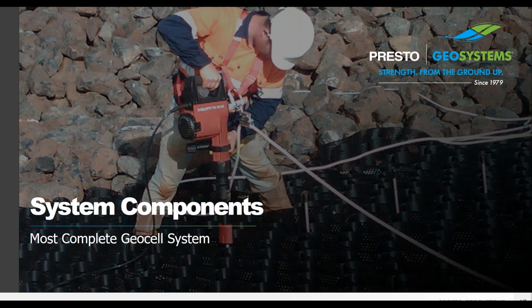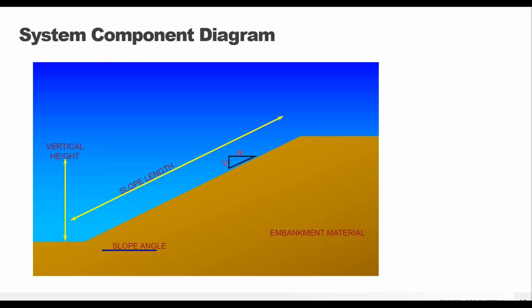Okay, so that's the actual GeoWeb panels, is what they're called. So it's a panel of all of those different containers all welded together. And you also are going to have additional system components. So system components are going to be all of the supporting pieces that help the GeoWeb system protect your slope surface. And again, ensure that uniform performance, uniform, keep that word in mind. And so it's going to protect against things like non-uniform deformation. It's going to protect against that erosion that we're trying to focus on, all of those different things.